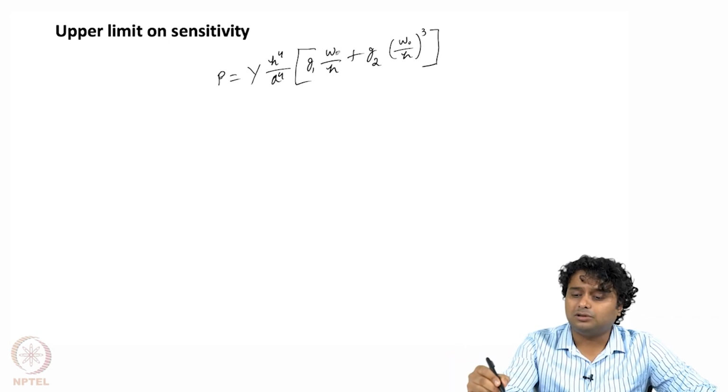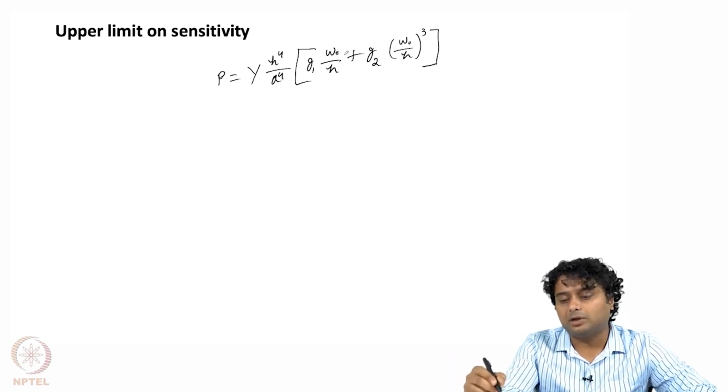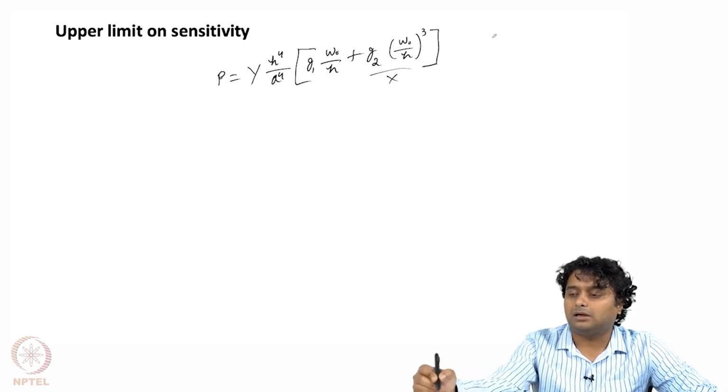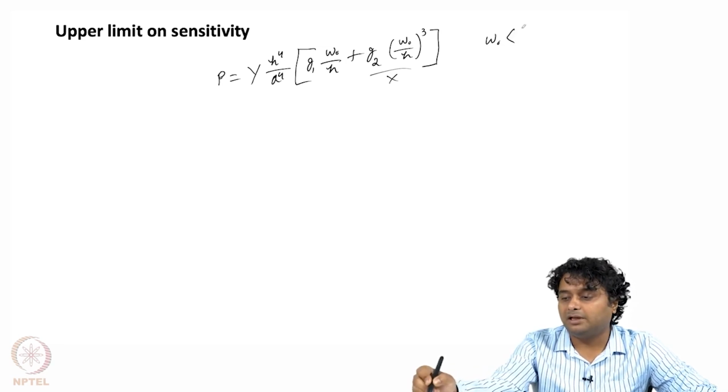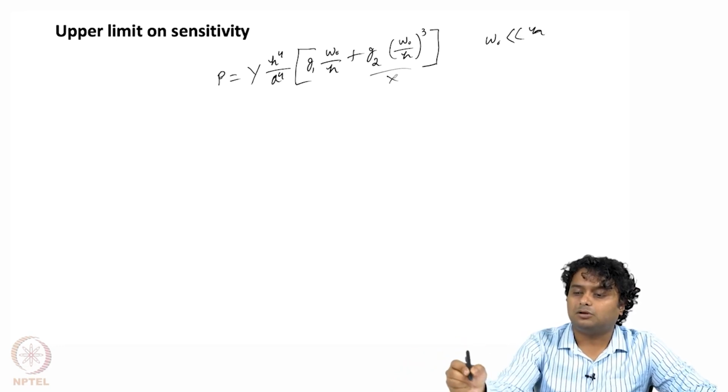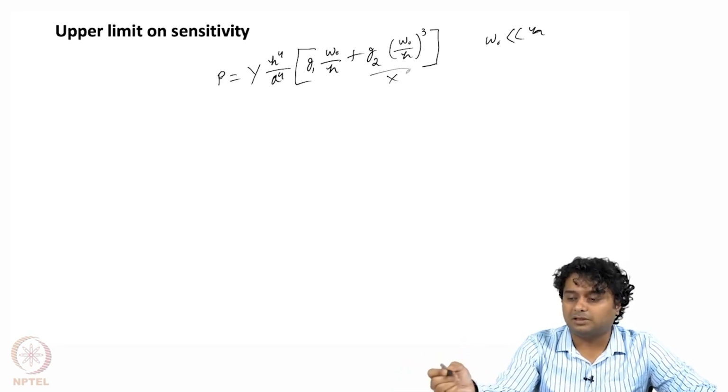This W0 is the deflection of the membrane, and for all the real cases where we deal with small deflection, we can neglect this cubic term, because W0 will be very less than H, so W0 by H whole cube will be much smaller than 1.